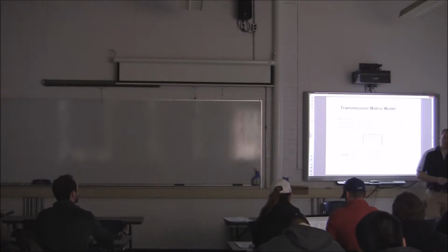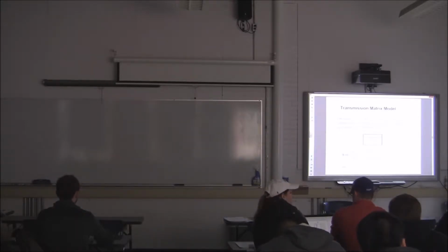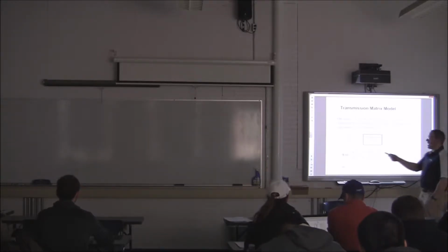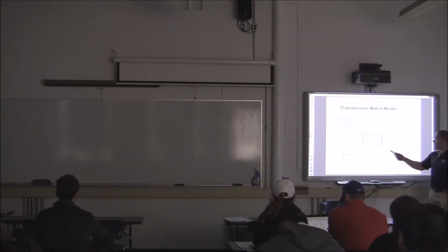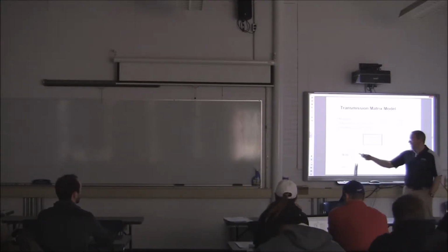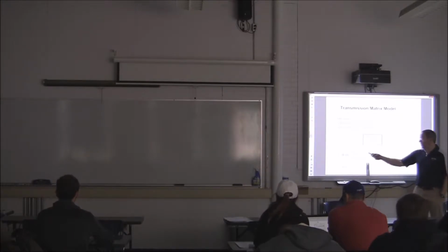This is something you may have seen called the concept of two-port parameters. Anybody remember that in their circuit analysis classes? Where you did a box and you analyzed it. These here are hybrid two-port parameters, and hybrid means the units are mixed, because you can see Vs equals A times VR plus B times IR.